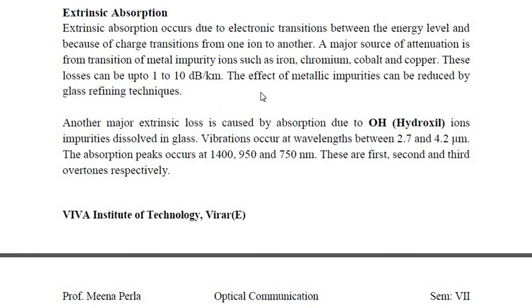The effect of metallic impurities can be reduced by glass refining techniques. Another major extrinsic loss is caused by absorption due to OH, hydroxyl ions, impurities dissolved in glass.